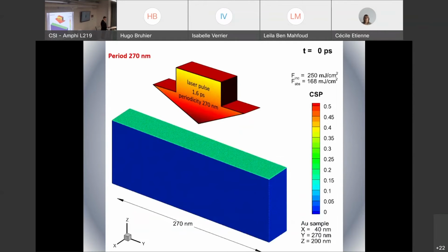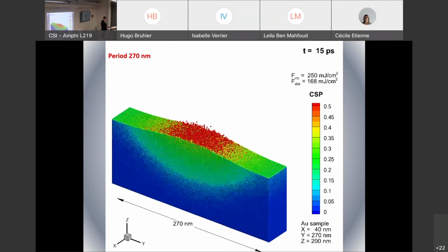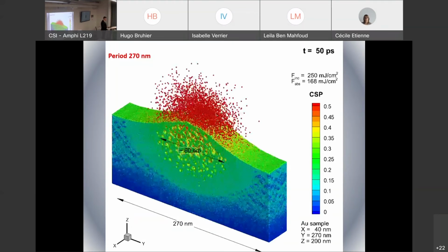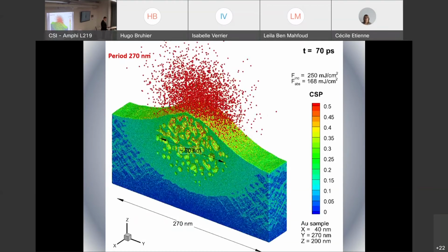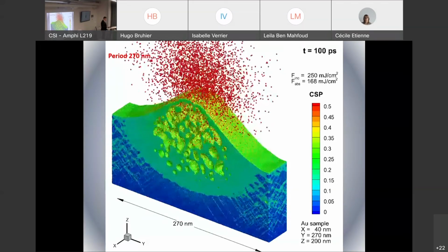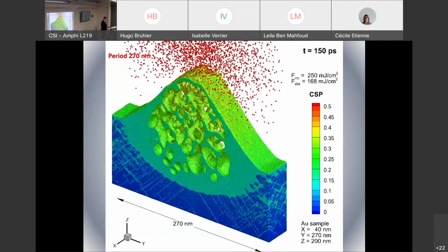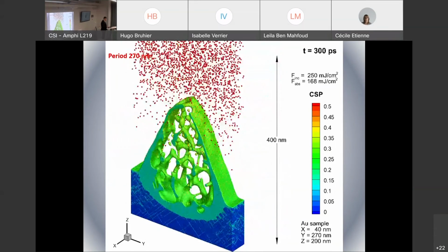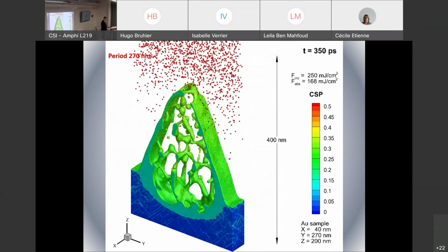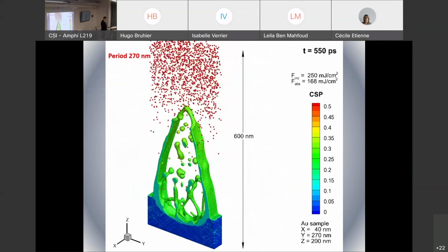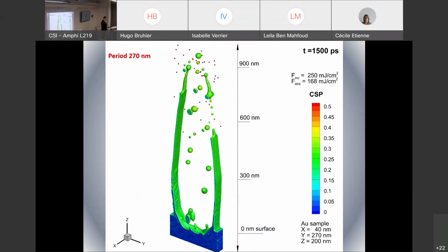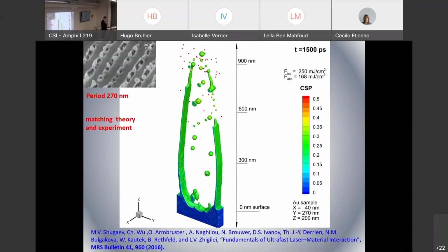And at high fluence we can observe how the structure forms, and we now have a significant amount of induced vapor. The dislocations grow in a much larger amount. The nucleation of internal voids, now the voids also contain vapor inside, but this vapor still has little effect since the momentum of motion of the structure in upward direction is really high here. So the structure opens up to the surface at some moment, which also corresponds to the experimental conditions and this applied fluence.